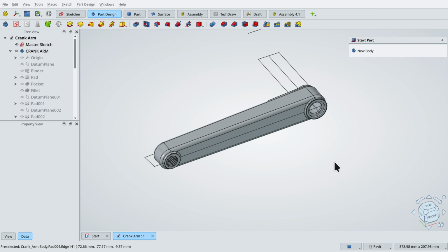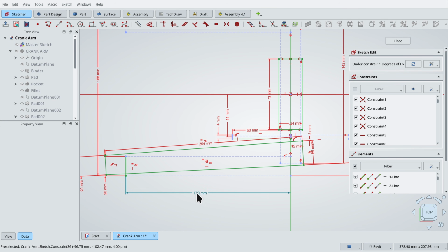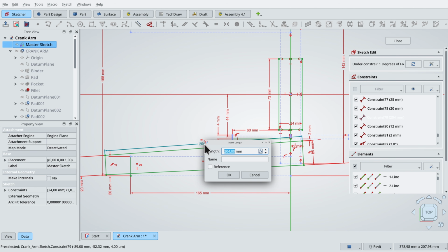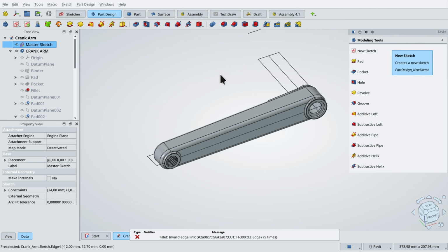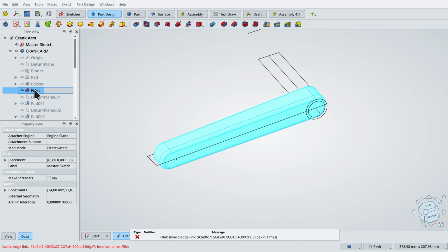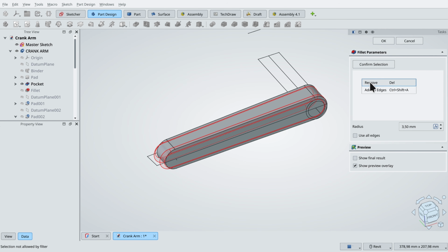The fourth ingredient is a big one. Be extremely careful with fillets. In FreeCAD, the Fillet Tool is probably the operation that causes the most headaches. It doesn't always behave the way you'd expect, and more importantly, it's very sensitive to changes. If you modify a sketch at the beginning of your tree, your fillets are often the first things to break because the software loses track of which edge was which. Always apply your fillets at the very end of your workflow and don't add them until the rest of the structure is solid.